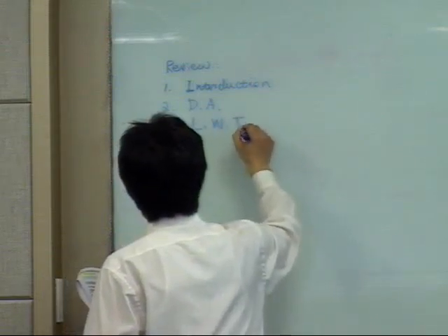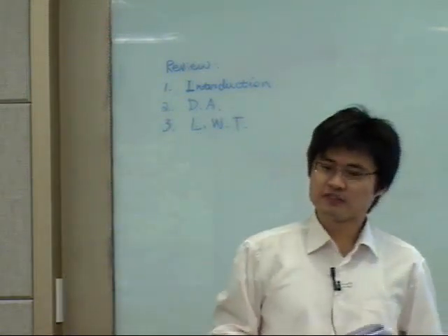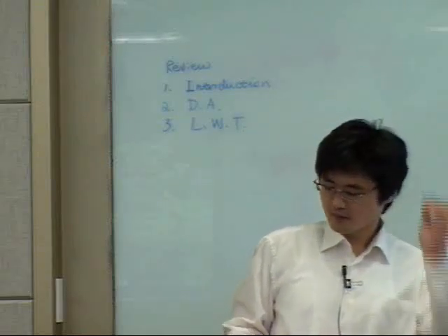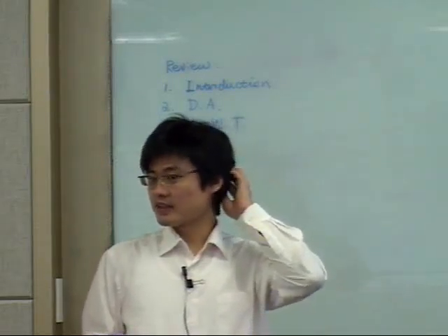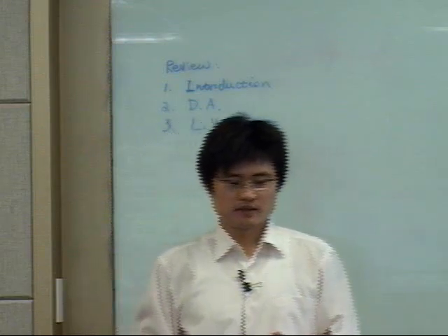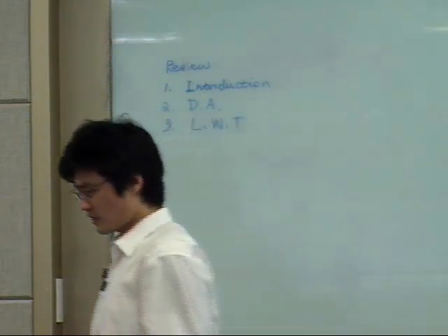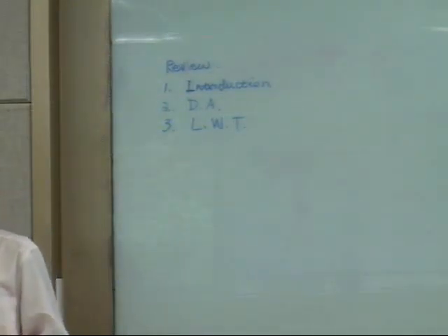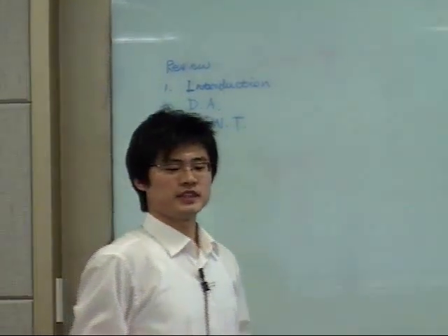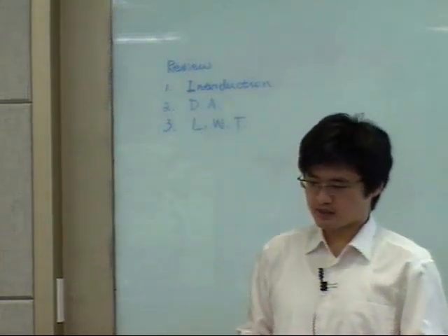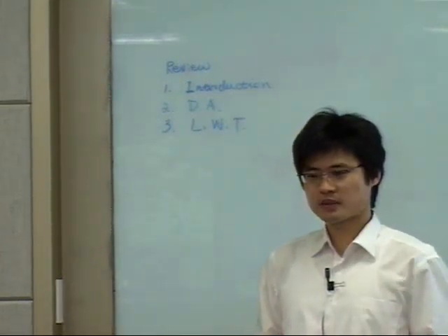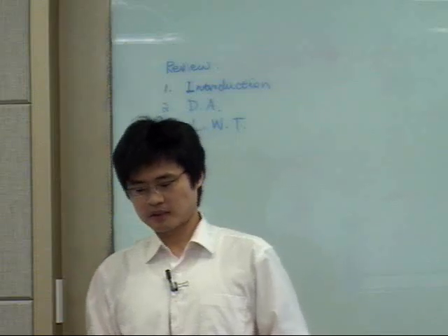And then I made a quick review of linear wave theory, the basics, the assumptions, a governing equation, which is the Laplace equation, another form of continuity equation. And then we had the boundary conditions, free surface boundary condition, sea bottom.